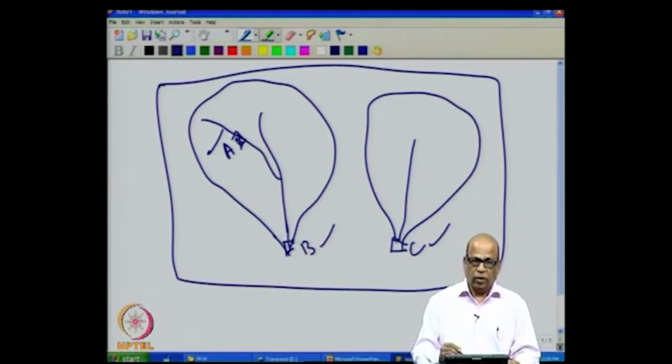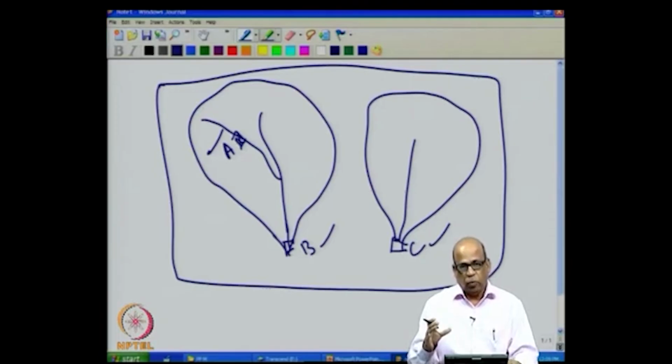So, when we are focusing our attention on the flows at site C, for example, the models will not only preserve the autocorrelations of the flows with respect to themselves across time, but will also preserve the cross correlations with respect to flows at B as well as with respect to flows at A. So, when you suspect that the flows have cross correlations and you would like to generate flows on these sites A and B, A and C, etcetera, then you need to look at multi-site models.